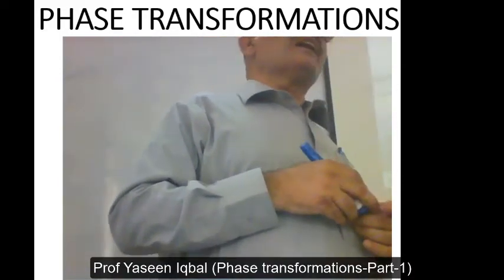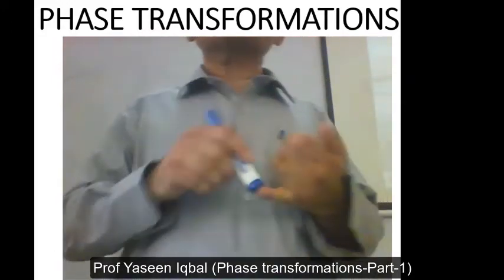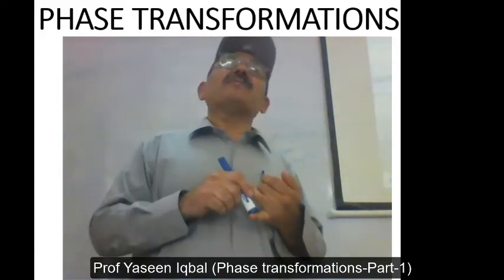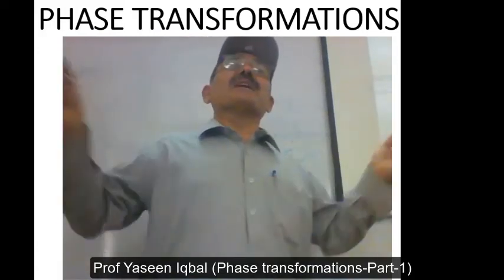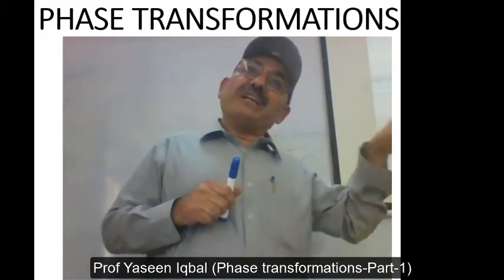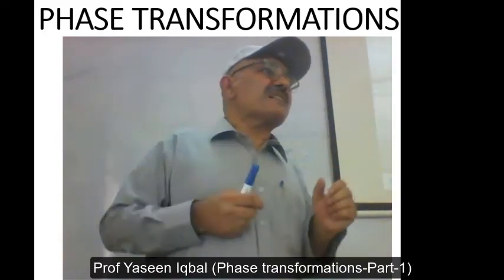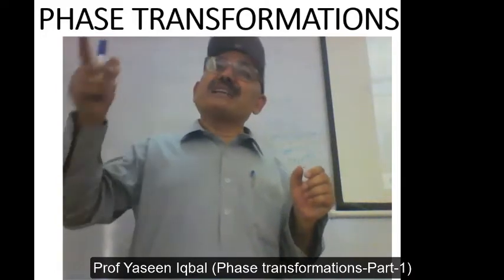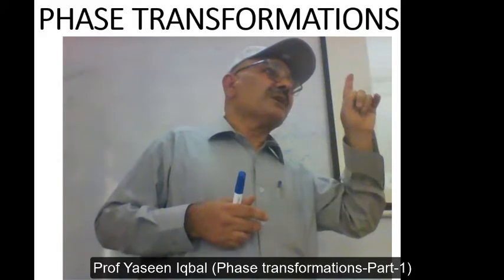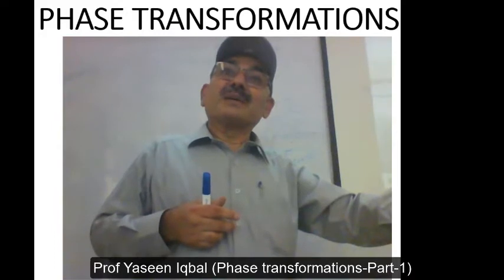Your material is 50% dense. If it is 50% dense, then what happens? 50% of the material has, for example, a dielectric constant 5000, which is the material which you intend to make. But the voids and the open spaces have the permittivity or dielectric constant of free space, which is 1. So the total dielectric constant will decrease to half, right?